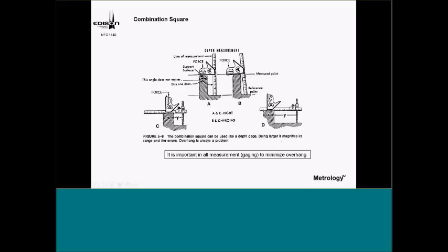And again, coming down, I'm showing to make sure you don't measure the top of the radius, that you're down here actually at your reference point, which is fixed. It's important to measure or gauge to minimize overhang.